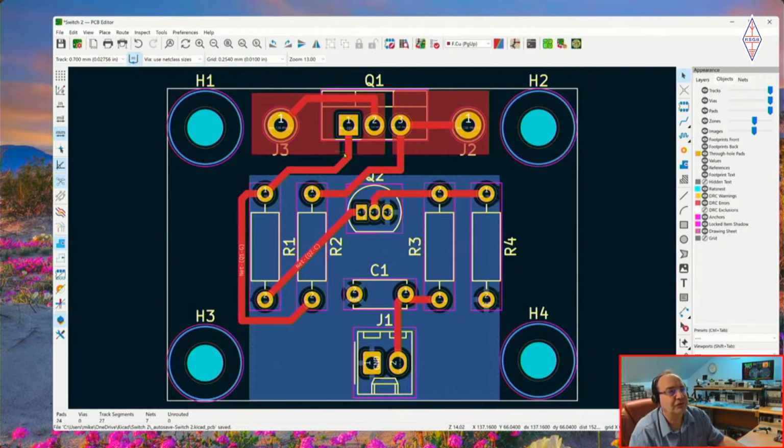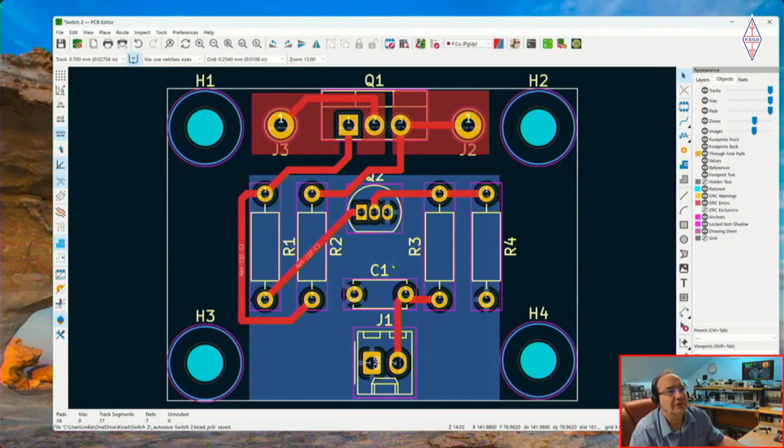Yeah, it is a good use of copper, and you can also get little PCB mounting heatsinks that you mount on the board. So transistors typically are turned on as switches; they don't dissipate much power, so you can use those with a relatively small area of copper because they don't need to dissipate much power.